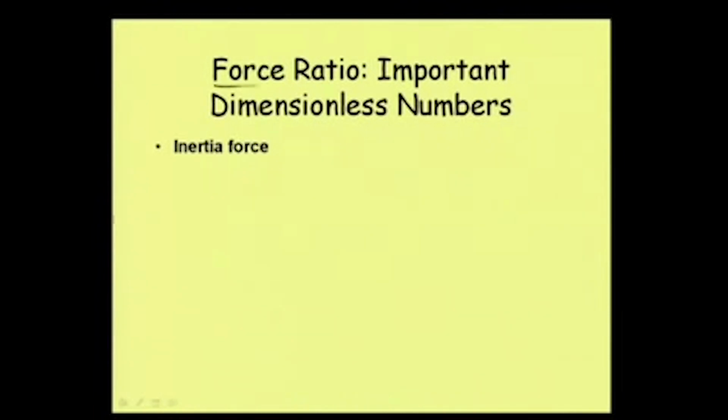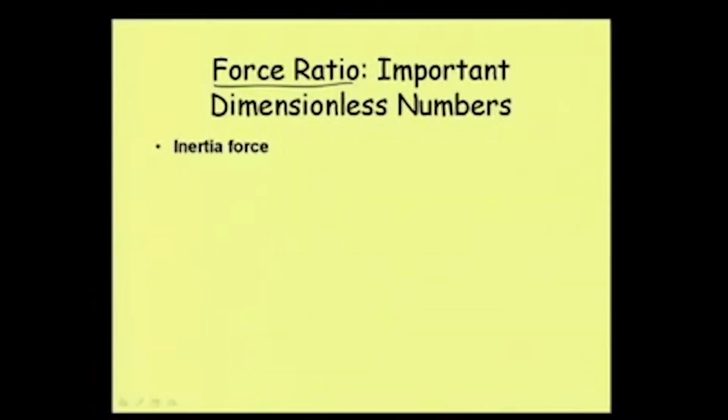Well, the force ratio: if we take the ratio of two forces, then definitely there will not be any dimension. Both are having dimension of force, so there will not be any dimension. So let us see what is the expression for inertia force. We can write quickly, inertia force is equal to mass into acceleration. So we can write rho, density, into volume, into acceleration.